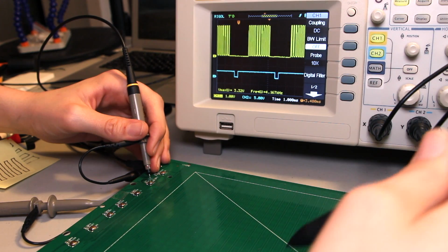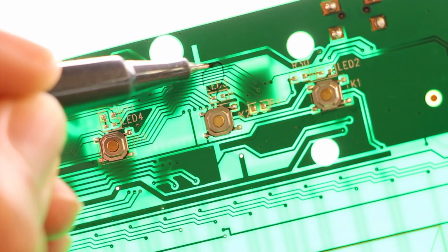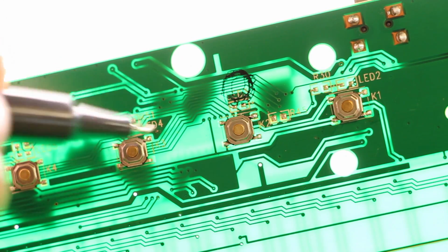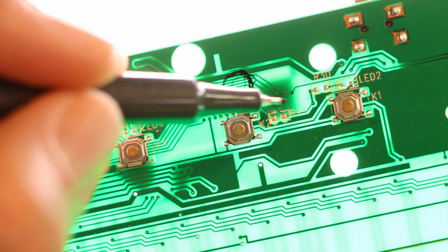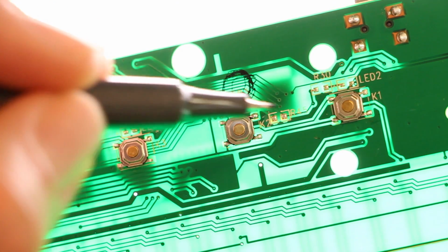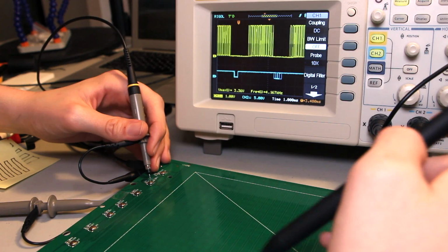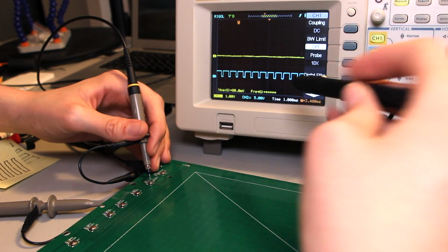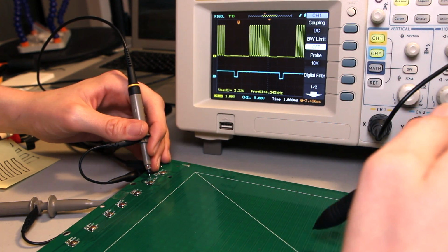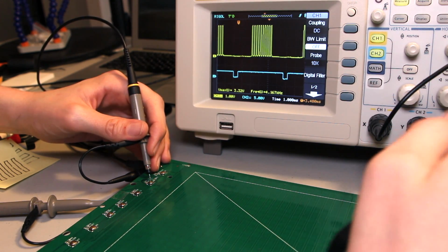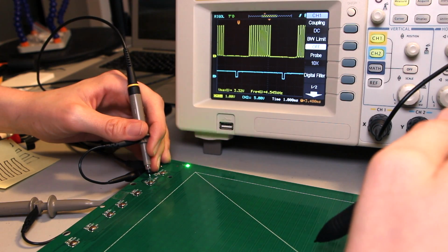So this analog front end has several outputs. This little bundle of 5 signals right there, going from the last stage in the analog front end through these vias directly under the microcontroller to its analog IOs. So in this experiment, the bottom trace is just being used to synchronize to the scanning waveform. It's just connected to an arbitrary enable input to one of the multiplexers.